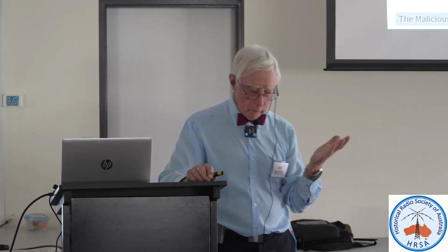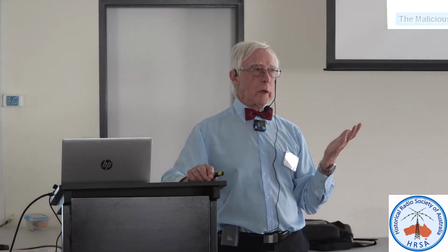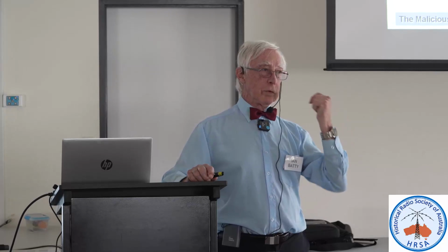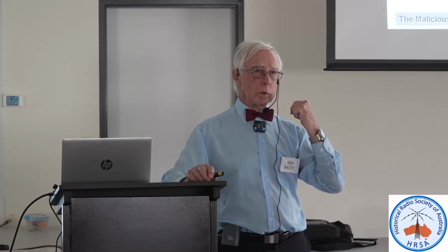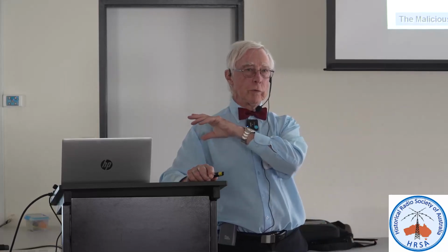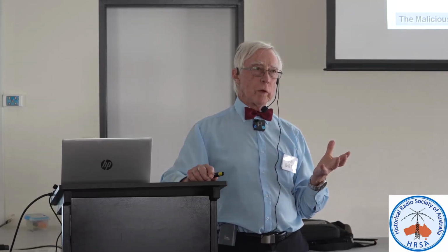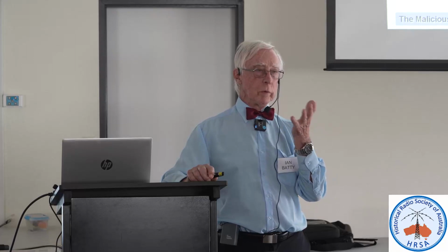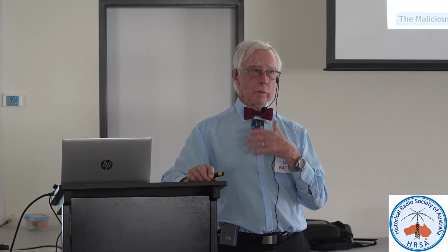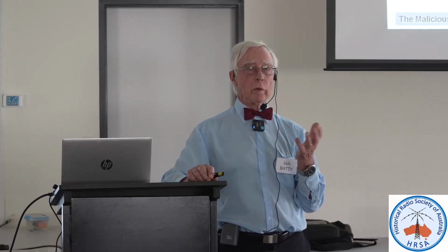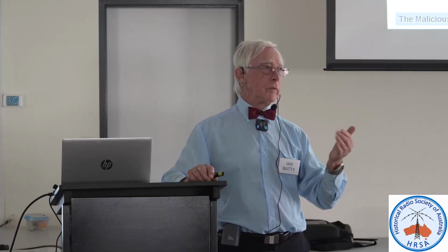So the reason I don't tend to recap is I don't know how long it takes to recap a radio. I reckon it's a good morning's work. For a set such as the Mickey, if you've had a look at the underside of them, it's a complete dog's breakfast. I don't know if you could do a recap without stripping it back to sockets, because there are so many components overlaid and in such inconvenient positions. So I guess I'm a bit conservative. I also look at the labour of doing a recap, and also the more work you do on a set, I guess my worst case analysis is the more likely you are to mess something up. But again, that's a matter of each of us having an individual particular strategy.